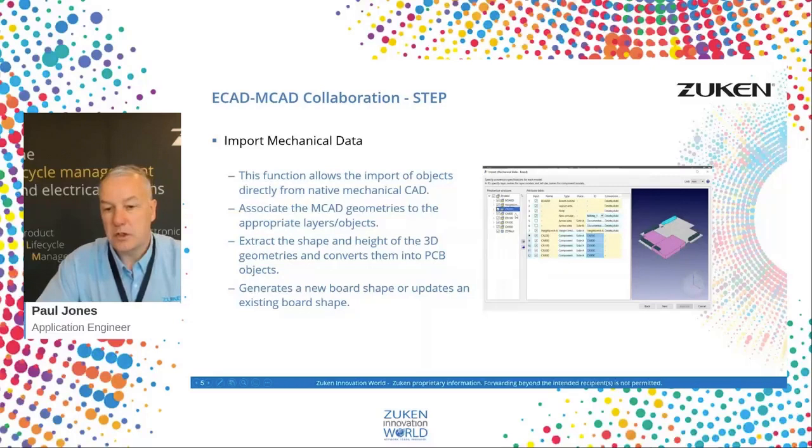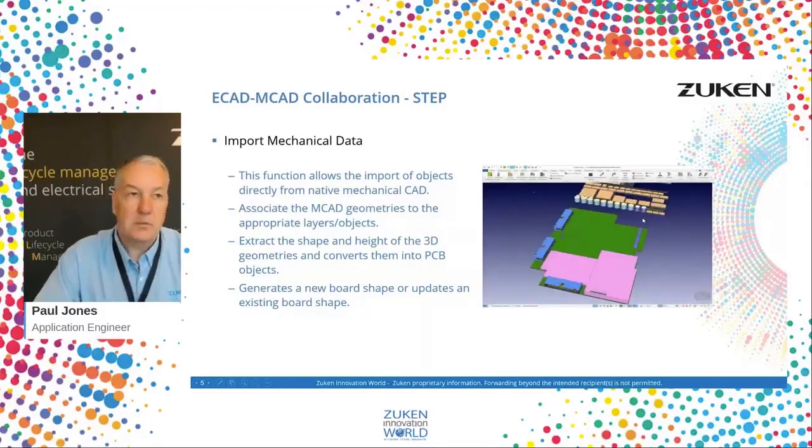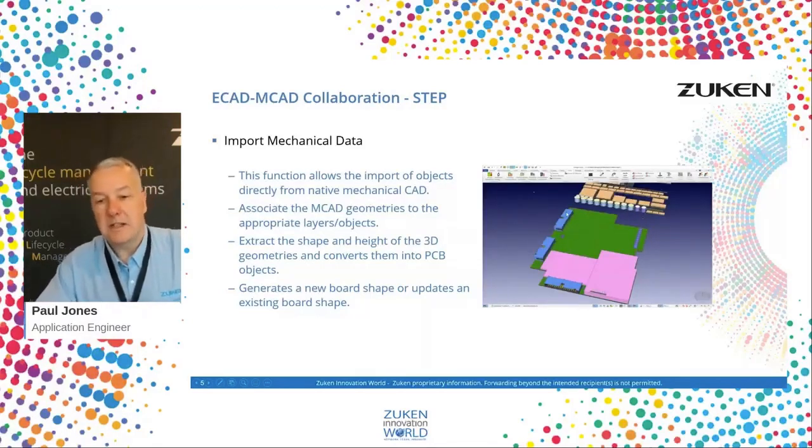Of course, what you can see here, I can cross probe from here as well to show which connector this is. For example, CN200, I can see it highlighted here. Once I complete the import, the connectors have now been placed and the height limits have been generated into these areas, and the rest of my components are ready to be placed.